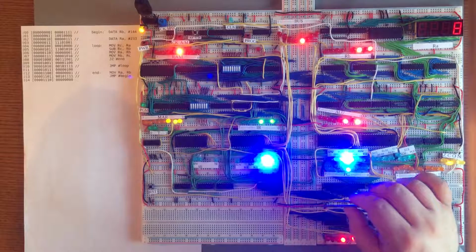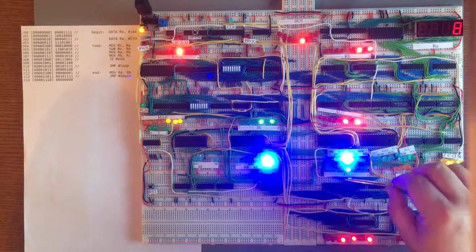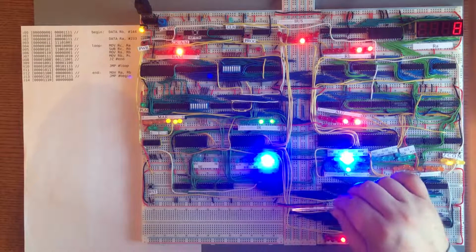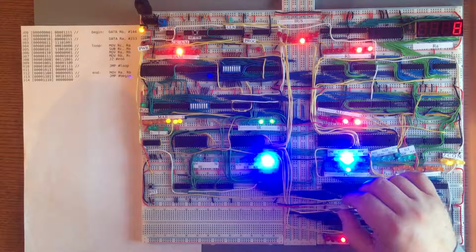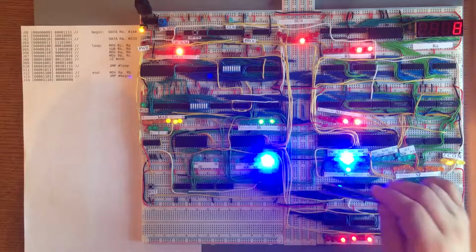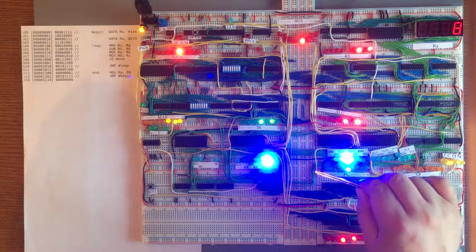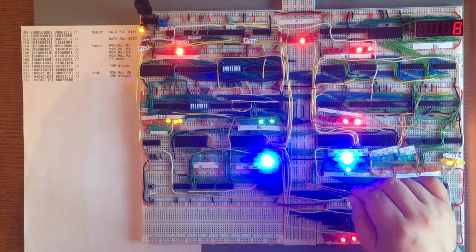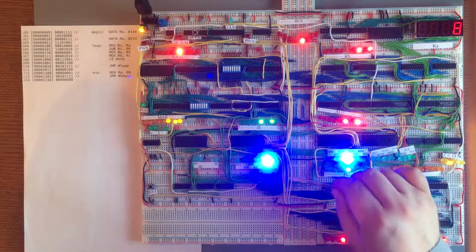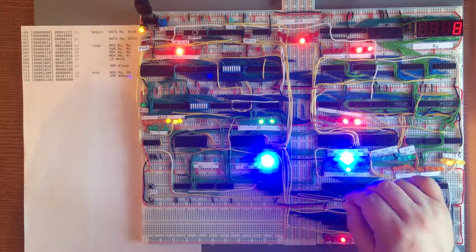And of course, that's not a good idea, because some other unsuspecting register might be trying to input a value from the bus, and so it would get 4 definite bits and 4 what we call floating bits. They wouldn't be connected to anything. And so what Ben did to remedy this situation is he has some pull-down resistors which are connected to every one of his 8 bus lines. And those resistors sort of force any line which is not being asserted to be 0 volts through that resistor.